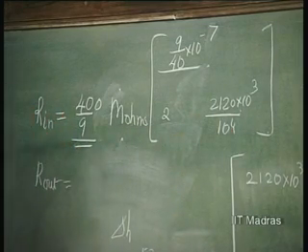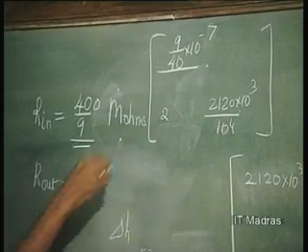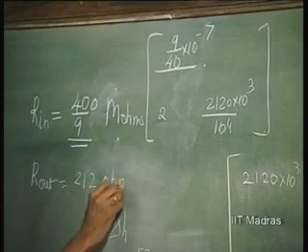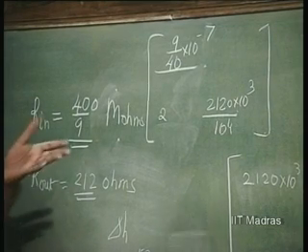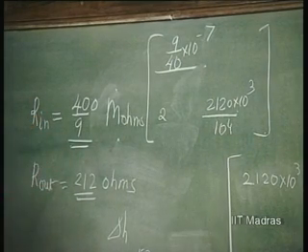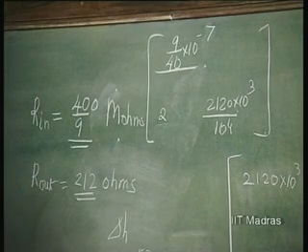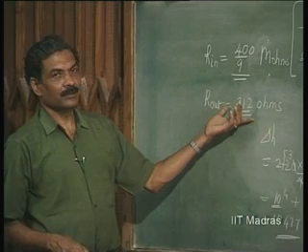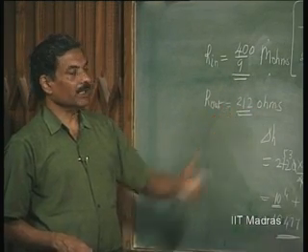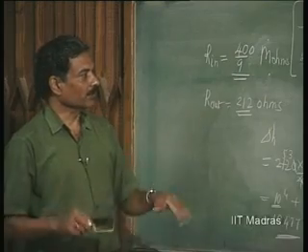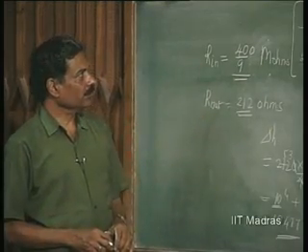Which is going to be 212 ohms. So, even though we have had an amplifier which uses 10K in parallel with 40K and 10K etc., we have now got an output impedance which is of the order of 212 ohms, pretty low. Okay. So, the output impedance is going towards 0, okay.